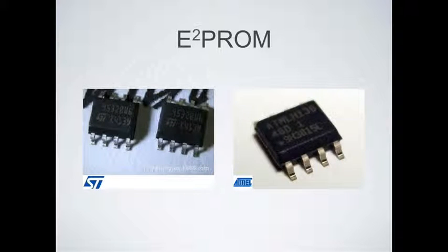So the next step up from EPROM was EEPROM. With EEPROM, we no longer need this UV cabinet. We can now erase the data electrically. You just supply it a high current, and once you apply the high current, it resets all the transistors for you. You use the same sort of programmer as you saw when we were talking about the PROM. That same type of programmer is what you would use to reprogram this EEPROM. So EEPROM is something that we've used for a while.